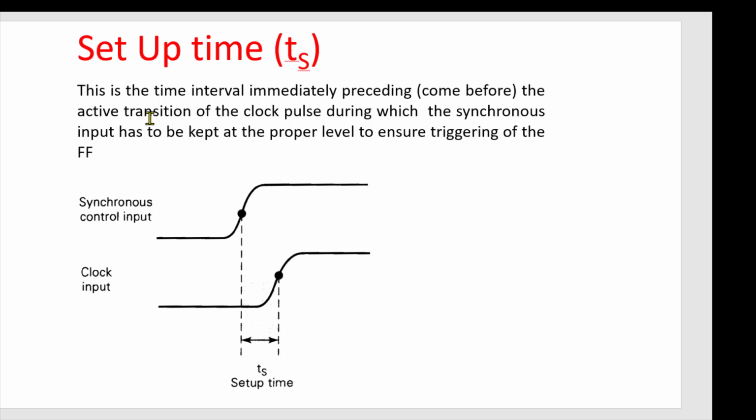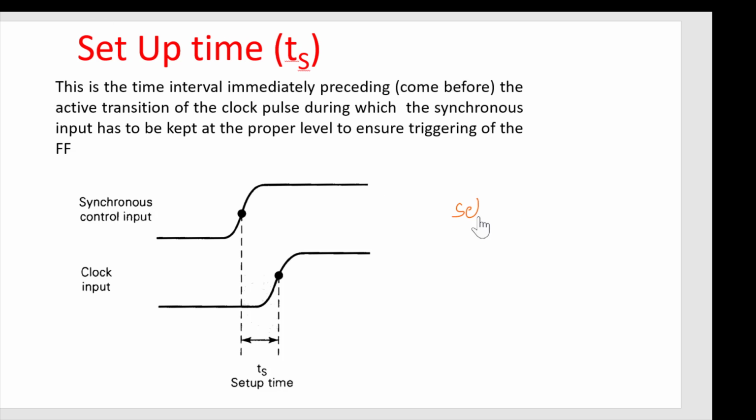First one is the setup time. The setup time is nothing but you have to keep your input constant for a certain period of time before your clock comes into picture.